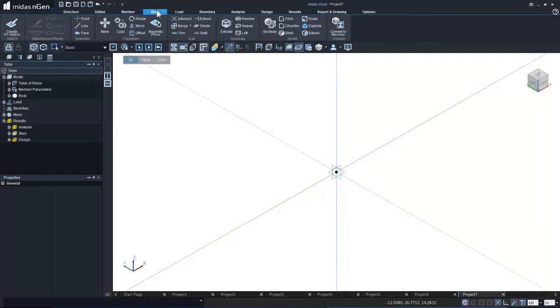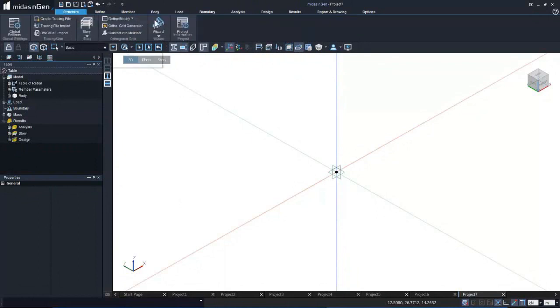And lastly, we have the body type of modeling. As in, you can simply create your lines, faces, points as you wish, like a sketch you can draw. And then you can convert those lines, those faces into members like columns, beams, braces, slabs. So it's actually very useful, and we have got all CAD type of tools for easy editing of the model. Also some generation tools are available, and Boolean cuts and all these operations are available for accurate modeling. So let's go ahead and start the modeling of our box culvert using the wizard tool.